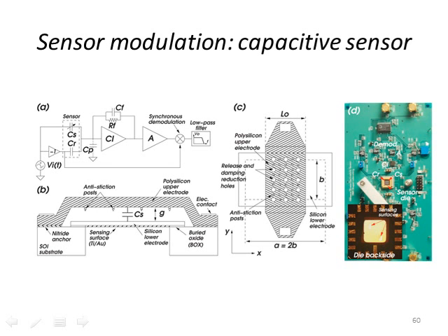We amplify, and then we do synchronous detection. So remember that this is a synchronous modulation. The modulation comes from the source located at the beginning of the circuit. After we multiply, we now have the change of the capacitance modulated at this higher frequency. We amplify, and then we want to demodulate by doing a multiplication again with the carrier frequency, and then we want to do low-pass filtering. And this is the circuit on the green circuit board on the right that allows us to do that computation.